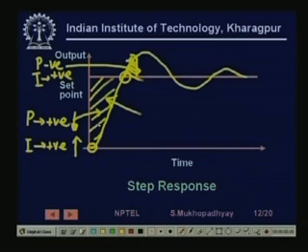So the overall net output is maybe still positive, so it continues on this journey, but eventually this integral value also reduces and the proportional controller value also becomes sufficiently negative. So the overall input turns negative and the plant turns to move. Now again the same thing happens here. Once it crosses this line, again it will oscillate. So you see that typically because of integral control there tends to be an oscillation, a high overshoot and an oscillation.